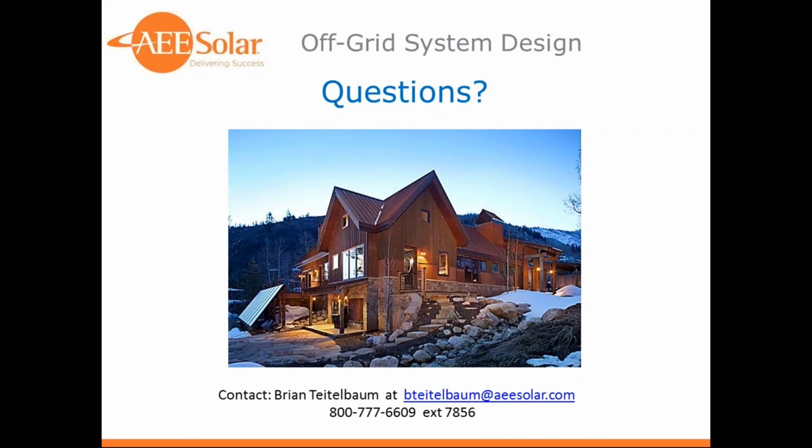We do have processes to equalize battery banks where you do a controlled overcharge to bring weak cells up to a higher state of charge to match the stronger cells, and that helps quite a bit. So with 2 strings, you already start to see some issues. You have some loss of the lifespan of the battery, although it's generally pretty acceptable. 3 strings is increasing that even more, but it's still considered an acceptable amount. By the time you get to 4 strings, it becomes really hard to keep all the strings evenly balanced, and you have really shortened battery life.